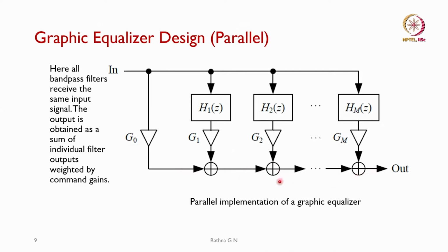So we have to check every time whether the output is overflowing, then scale and take care of all the overflows. So it is better to go with the cascade section in hardware than the parallel structure, although we have both. If you are able to take care of the overflow coming from the addition at the input itself, then we can use the parallel section, because it is much faster compared to our cascade section.